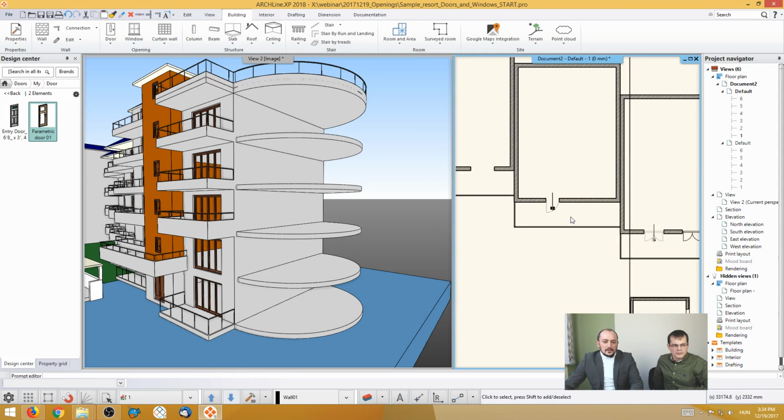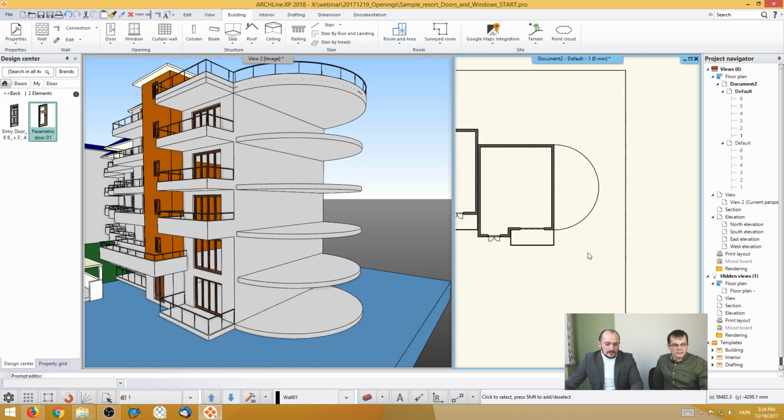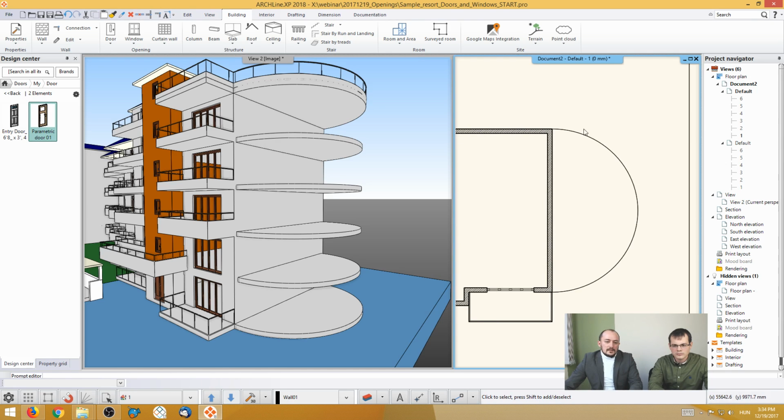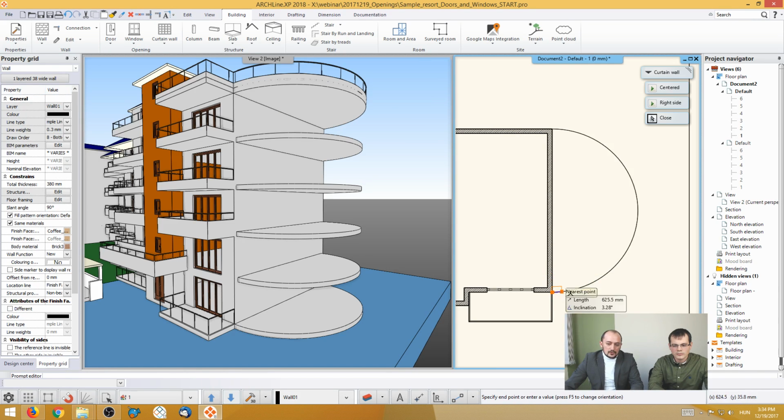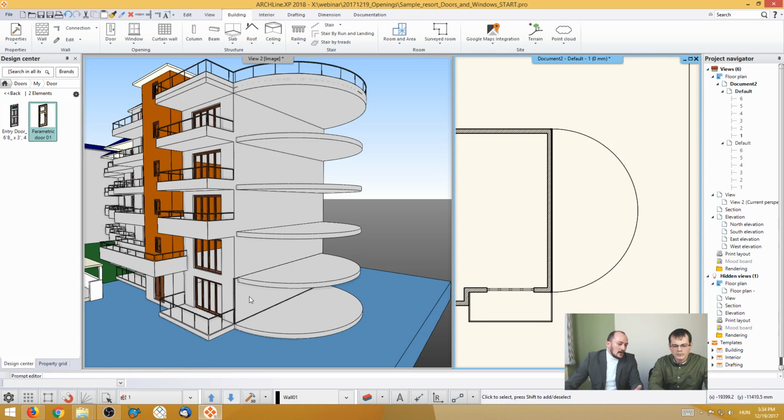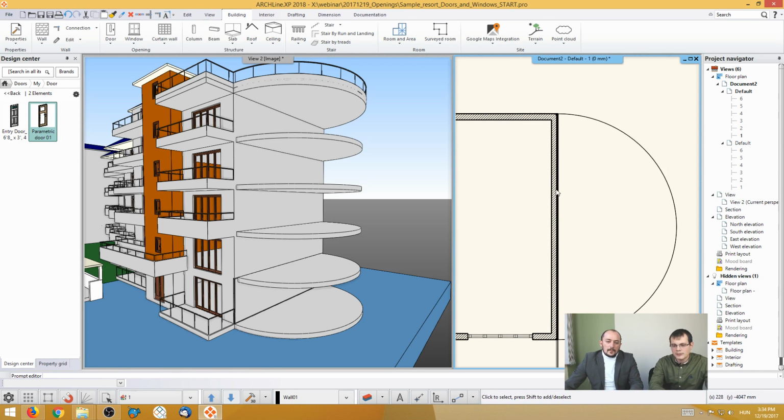First, if I go to this part of this drawing, I think now I'm on the first floor. Yeah, let's just check it. So I'm actually here. If I would like to create a curtain wall, I can go with the curtain wall tool and go with the first one, which allows me to literally draw a curtain wall. And then, now it's inside the existing wall. Yes, it's overlapping with the existing wall.